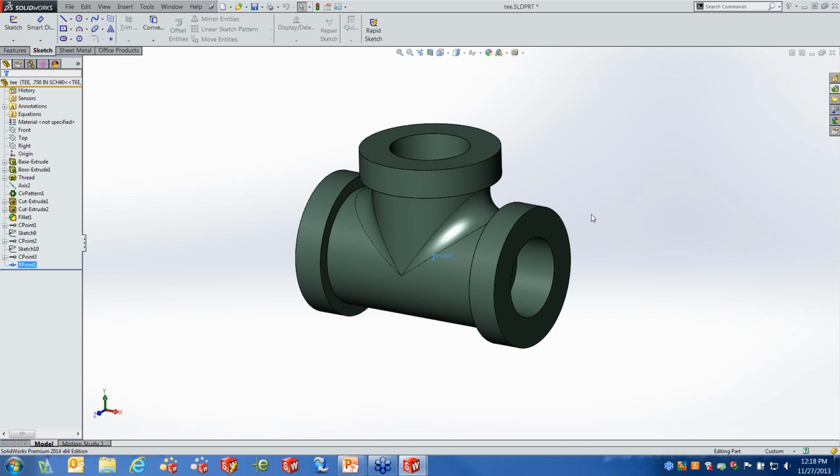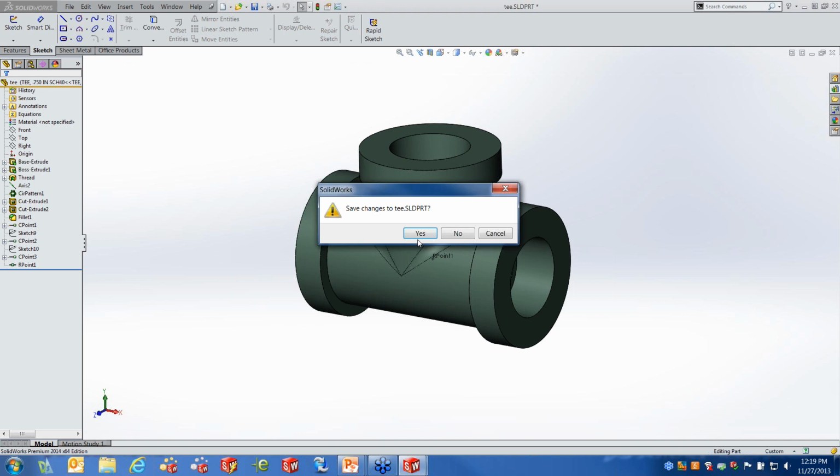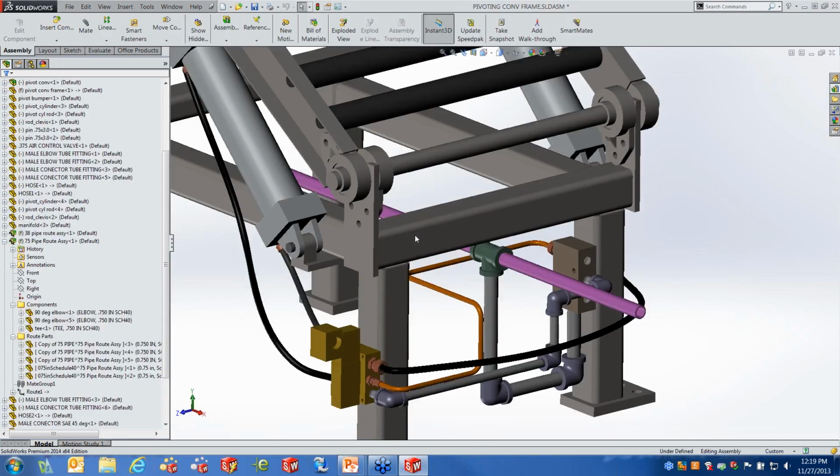So all of our fittings, all of our inline valves, all of our flanges, really everything that we add to a route inside of routed systems has these connection points and route points. So there's some intelligence that has to be added. Now, the libraries and the stuff that I'm using today all has that intelligence built right into it. Okay. Now, the route